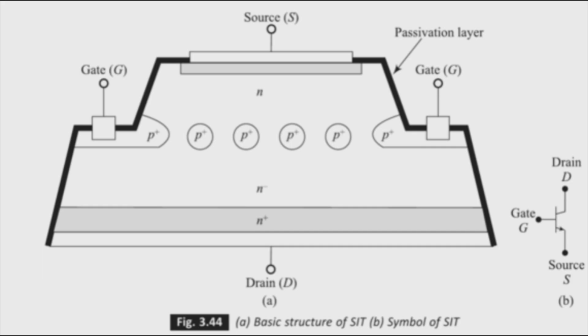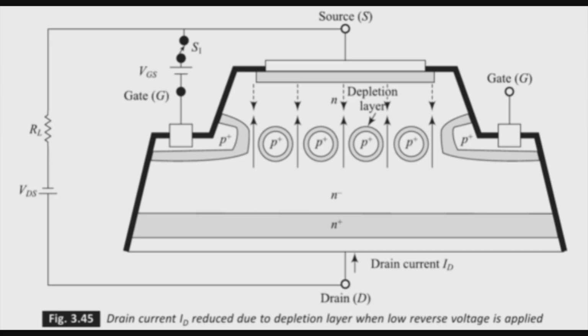There is no sharp threshold voltage. There is no digital on-off switching. This is a purely analog control process. If we examine the ID-VDS characteristics of a JFET, we can see that the curves do not flatten completely. There is no hard saturation region. The drain current still depends on the drain voltage, resulting in behavior that is very similar to that of vacuum tube triodes. This is why we often say that a JFET exhibits a triode-like characteristic.